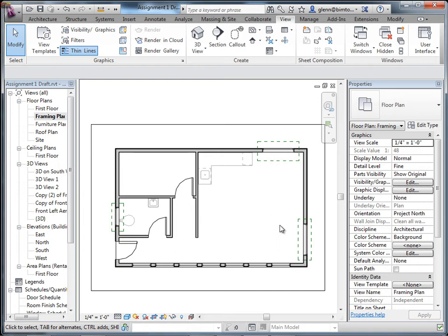Within that, I'll often have a secondary dimension string that'll go from here to all the intersecting walls. So I'll sort of do the intersecting ones in here. I go here to here, and I do that. As a third string sometimes, I'll actually dimension to the windows, the center lines of windows. But you often have strings of dimensions, different strings that kind of all relate them together. Let's think about how you can do that.